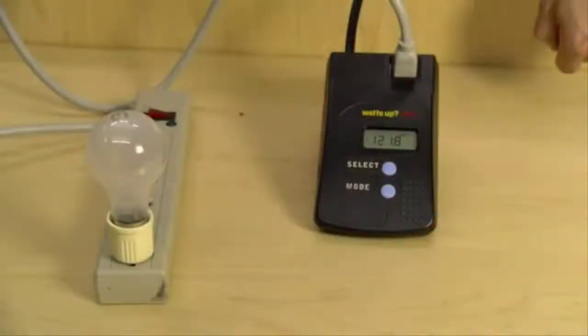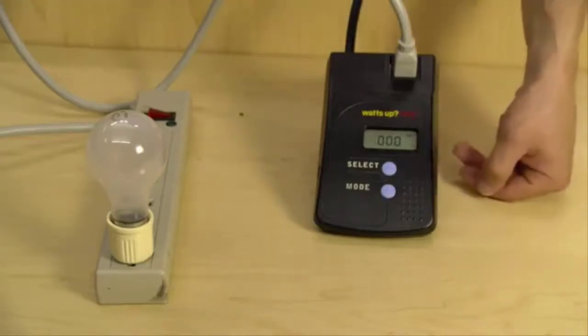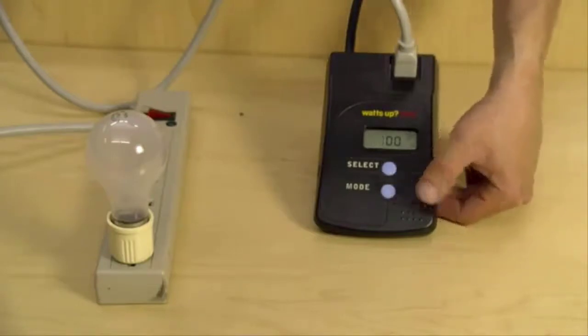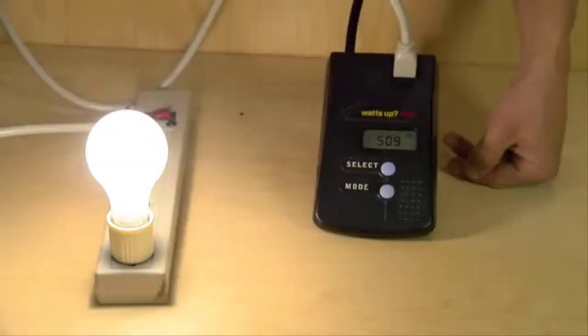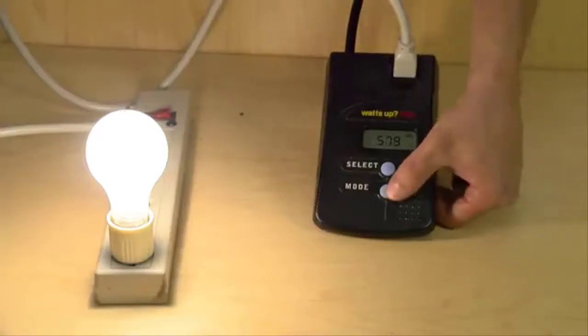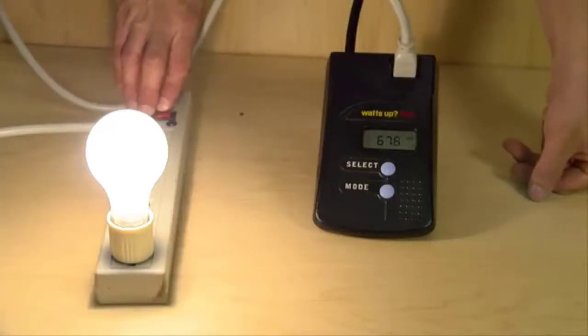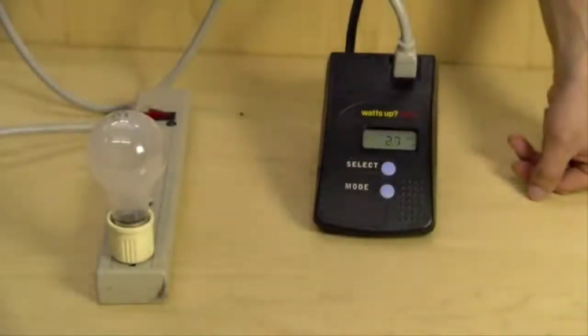In this example, I've plugged my light bulb into a watt meter, which shows the system voltage is approximately 120 volts, but since it's off, there is no current, or 0 amps. Once I turn on the light bulb, the current measures 0.509 amps. It also tells me that the wattage of the system is 67.7 watts, which is close to the calculated value within error.